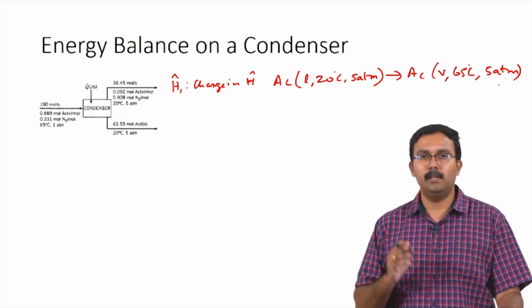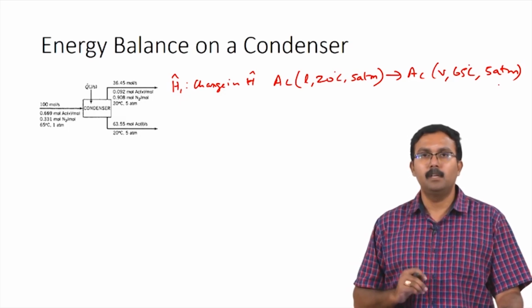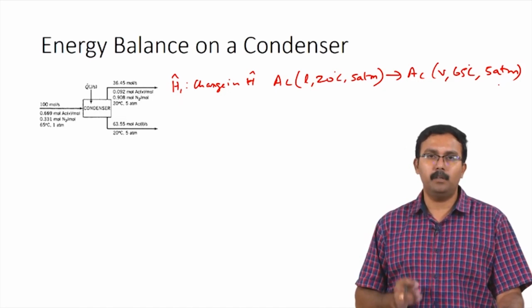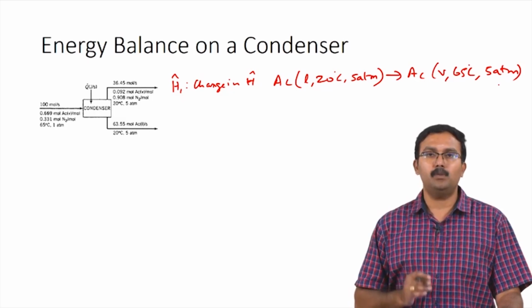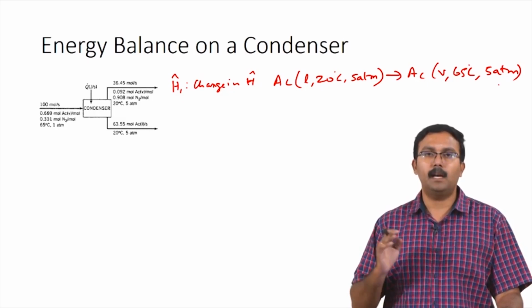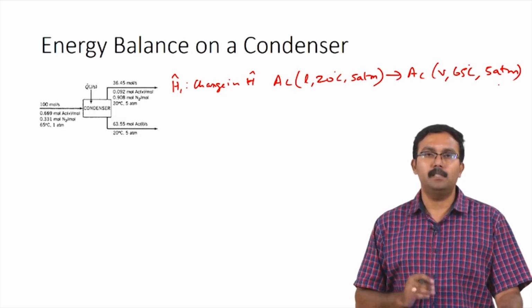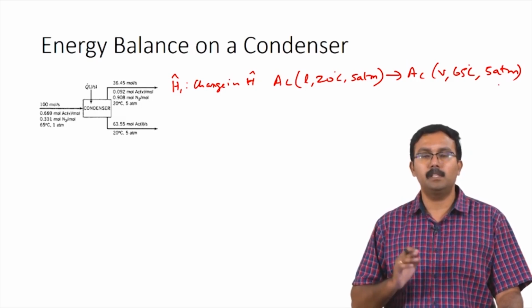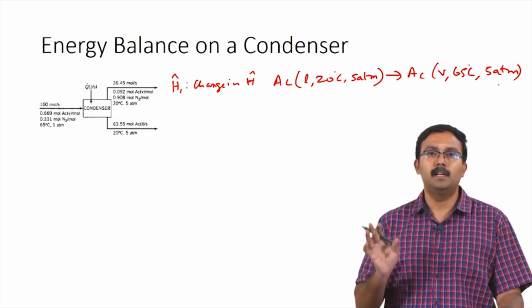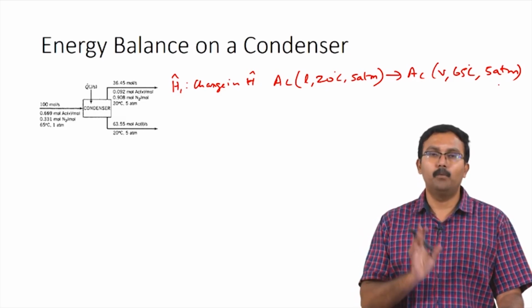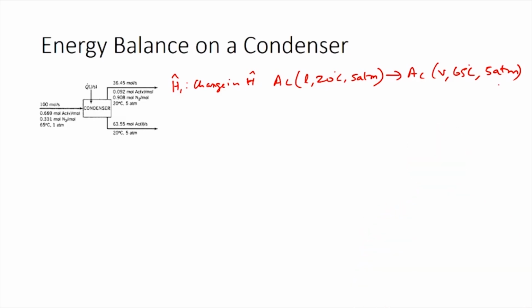So, here you have liquid getting converted to vapor. So, we need to identify the boiling point of acetone, and one of the steps where the phase change happens has to happen at boiling point at 1 atmosphere. So, this means the hypothetical path would also have to include pressure changes, so that the process would have the step where phase change happens at boiling point and 1 atmosphere. So, the boiling point for acetone is 56 degrees Celsius. So, this can be looked up any table.